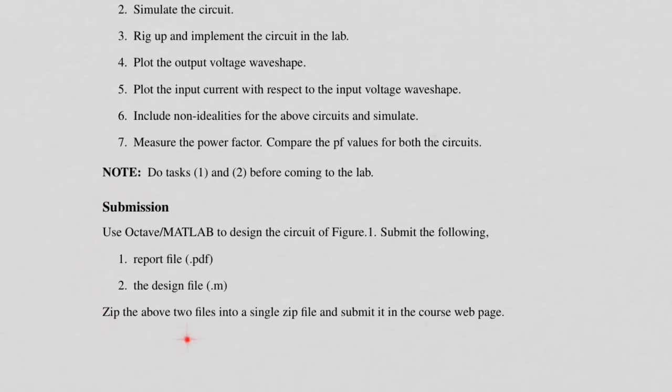And typically a submission to your instructor should be of this fashion. You need to submit a report file, which is the way you have done your lab circuit implementation, and the tabulations, the specifications, and the results, oscillograms, should be put in there along with your conclusions. This is the design file, which I said you can use Octave or MATLAB and put in the equations so that you can do iterative design for any given specification, and give these two to your instructor as part of your lab work.